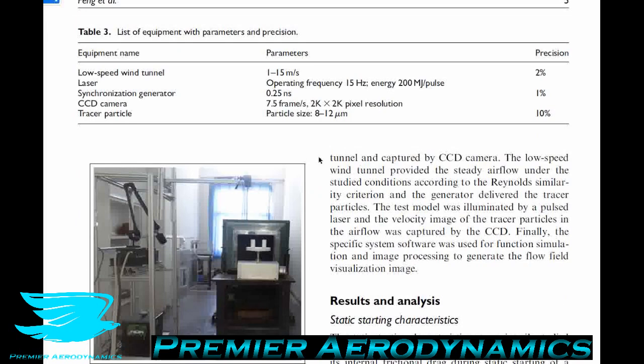So this is a pretty decent size. These particles will fall out of the air within about an hour, but they are okay in terms of PIV. So in terms of PIV, the particle size is, again, a balancing act between having them small enough so that they follow the flow faithfully, which means that they will follow the flow as they should be doing, and they will stay in the air, but also large enough that they will reflect the light.